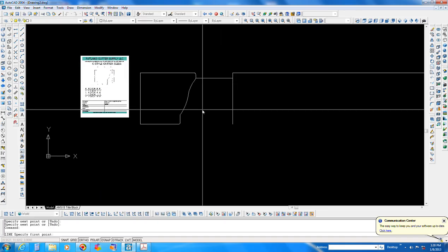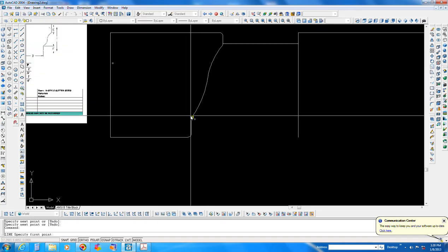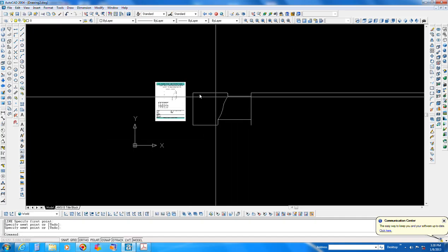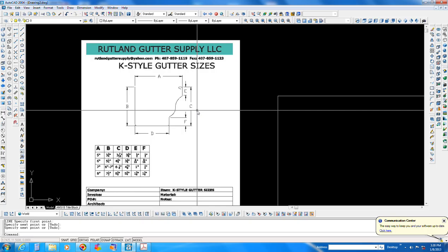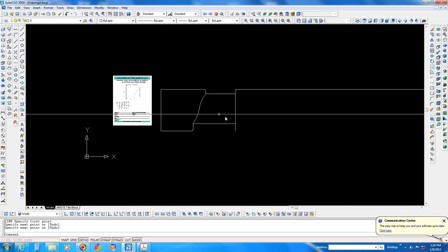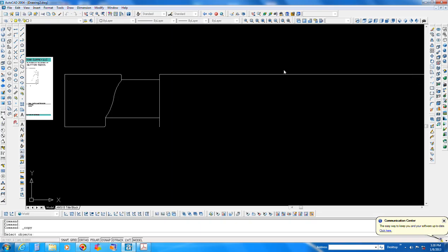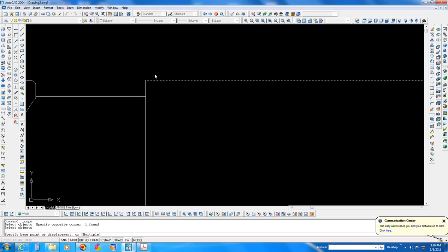And we'll come across like that. That's pretty much what you're going to see from the front. It's wherever it flattens out. Like I said, we're more or less trying to get to the assembly view. So now what we can do is copy this line using the copy command and the icons. We pick the object, right click to hit enter. We'll pick the midpoint.